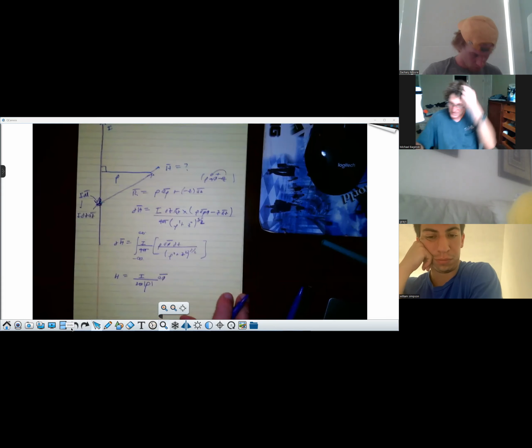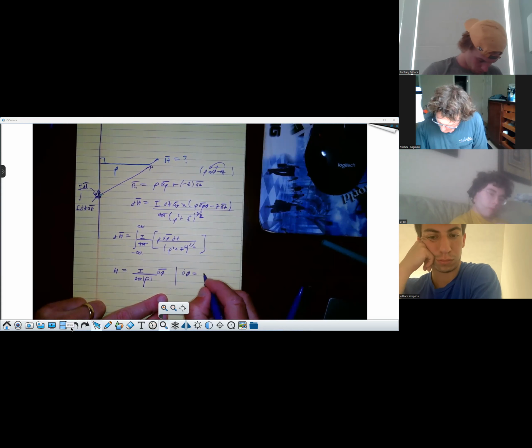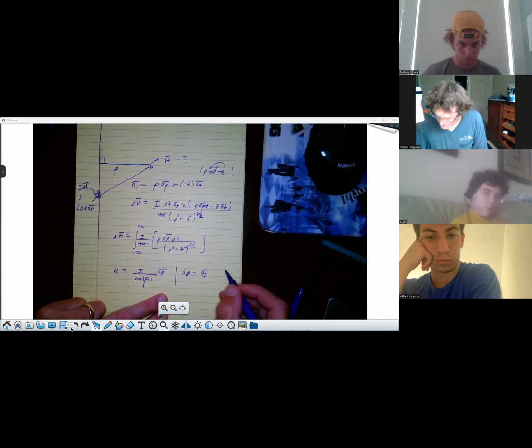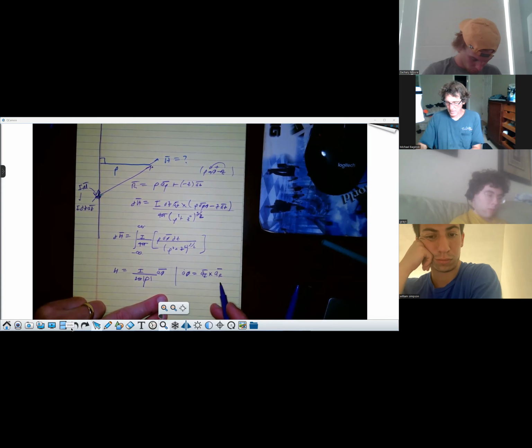But I have to make mention of what A phi is. A phi itself, this is important. A phi is going to be equal to AI, a unit vector in the direction of I, crossed into AR, a unit vector pointing from where the current is, or I should say the direction of the current element, to the point. Now, the reason I'm saying that, and I'm going to get to this in a second, I want you to pay attention to this point.